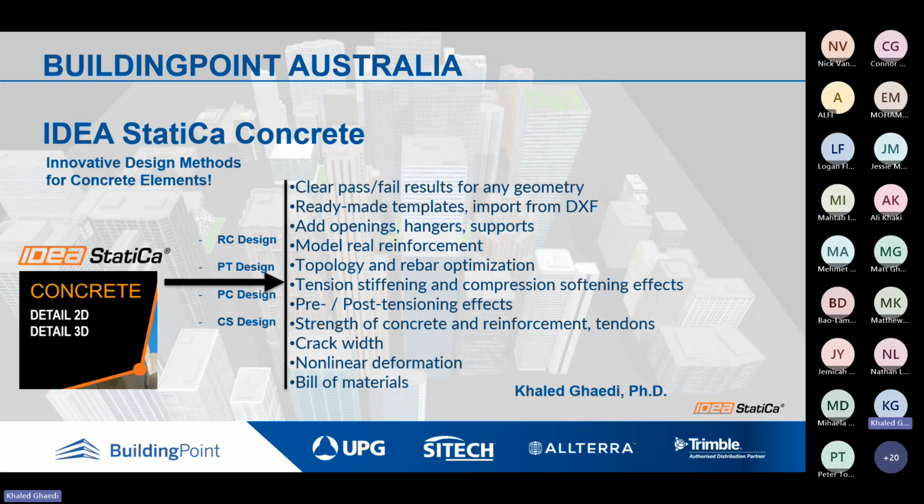Here I listed some of the main features of detailed 2D that you can always take advantage of. You can add openings, you can check the strength of the concrete, reinforcement and tendons, you can check the crack width, and also see the nonlinear deformation, and at the end of the day you can get the bill of materials as well.